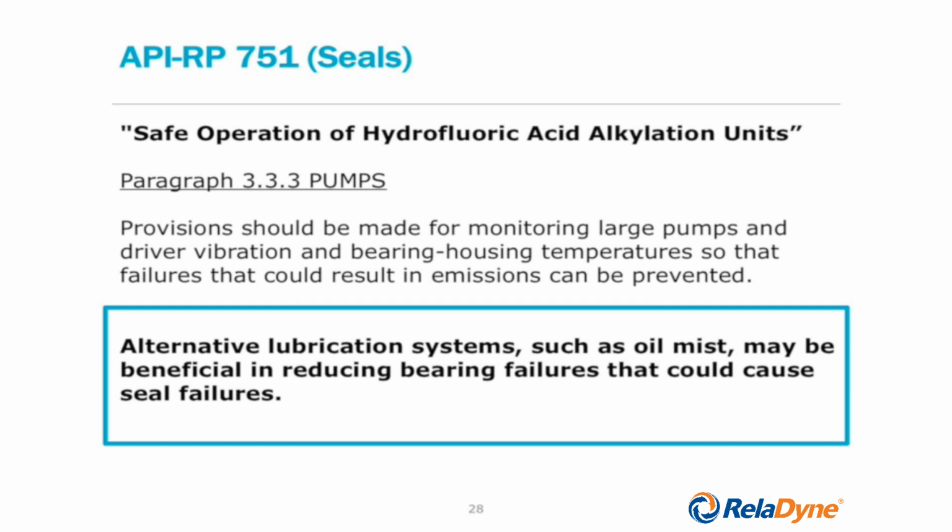It's an API standard that covers mechanical seals, and it's especially relevant and important to have good mechanical seals in such units as the hydrofluoric acid alkylation unit. We call it an alky unit very frequently. There's a paragraph in that standard, paragraph 3.3.3, which says provision should be made for monitoring large pumps and drivers so that vibration is not excessive and so that bearing housing temperatures are not excessive, because we want to have zero failures that could result in emissions of this very dangerous fluid.